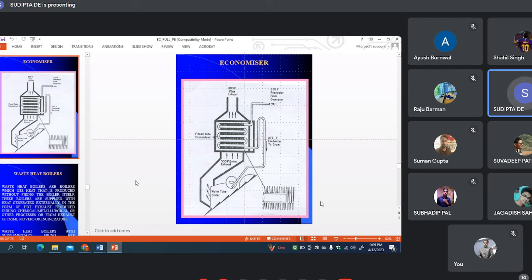Evaporation has to be done in a drum type structure if it is a subcritical boiler. Two drums, top drum and bottom drum. Sometimes they call them steam drum and mud drum. Then there are two rows, or rather several rows of tubes connected to them. The lower temperature sides are called downcomers, and the higher temperature side is called risers. I'm not going to describe the boiler now, it's not my class, I'm of power plant.